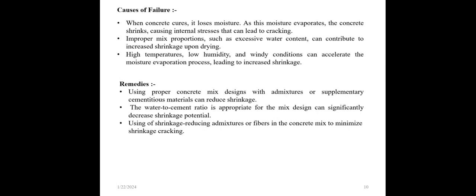Remedies: using proper concrete mix design with admixtures or supplementary cementitious materials can reduce shrinkage. A water to cement ratio appropriate for the mix design can significantly decrease shrinkage potential. Use shrinkage reducing admixtures or fibers in the concrete mix to minimize shrinkage cracking.